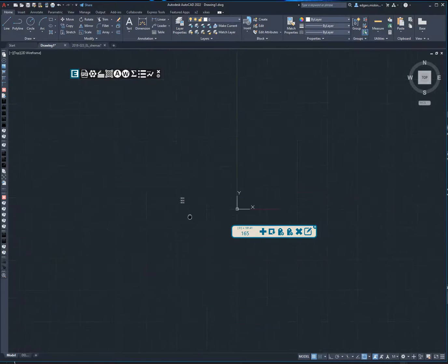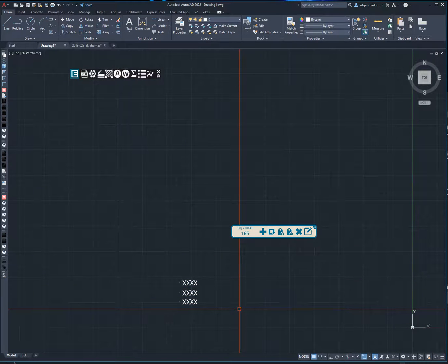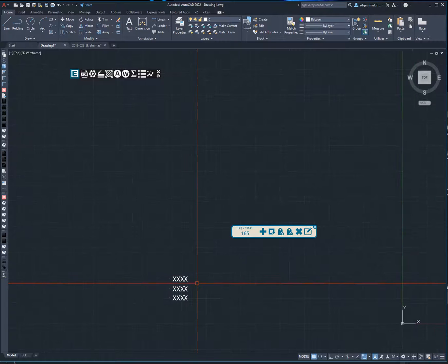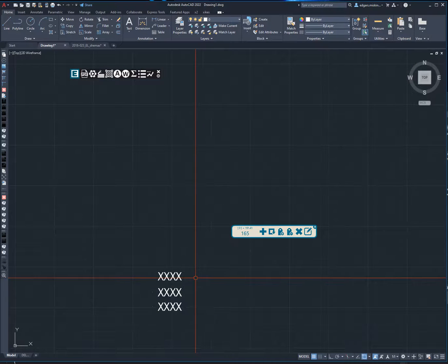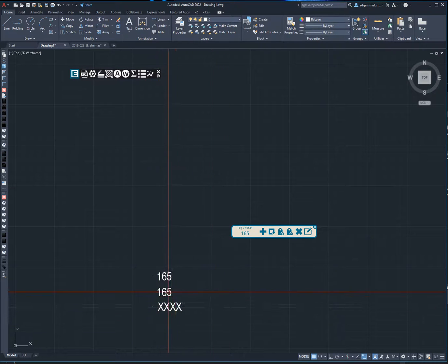Now we also often need to note this number down in some kind of schematics or in some kind of text or whatever, and that is usually done in a block attribute. So I also have a button that writes this value in a block attribute. I can just click it here and click on the attribute, and it inserts the number in there.